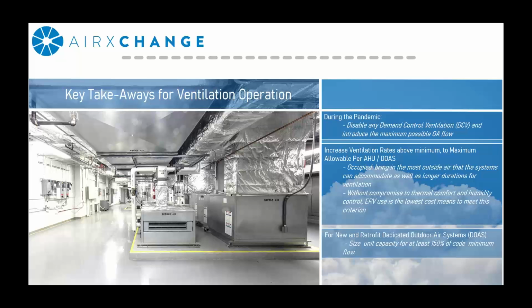Also, you're probably not going to want to use carbon dioxide as a reference of whether or not you're achieving proper airflow. My suggestion would be to use the actual airflow of the unit and compare that to the rates specified in 62, as carbon dioxide can be a tricky gas to use to determine the quality of the air. Increase ventilation rates above the minimum rates to the maximum allowable per device without compromising thermal comfort and humidity control. This can be a little difficult, but we're going to talk about some ways that you might be able to do that.